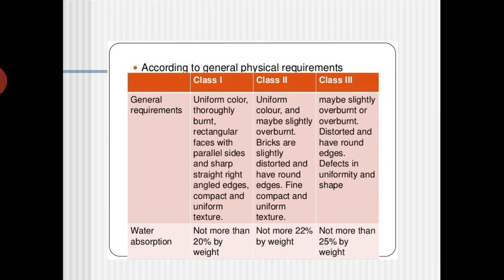It is thoroughly burnt. It has rectangular faces with parallel sides and sharp, straight, right-angled edges, meaning it is properly cut, and a uniform texture also, which is very important. The second class has uniform color, of course, and is maybe slightly warm burnt. It is not completely burnt, because one criterion is very important in this,